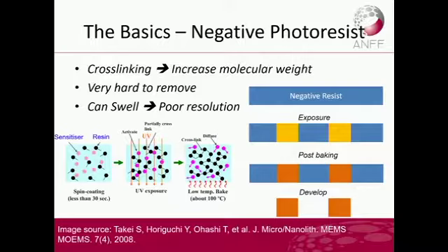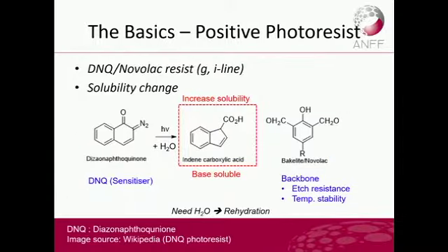That means your resolution could be limited. So the industry really quickly ditched negative resist in about 10 years' time. These days, if you wanted to work with the semiconductor industry on a photoresist project, and you bring up the name negative resist, they would definitely say, no, we don't want this. And if you bring up a solvent developer, they will also say, no, not possible. So they are only happy with positive resist and aqueous development.